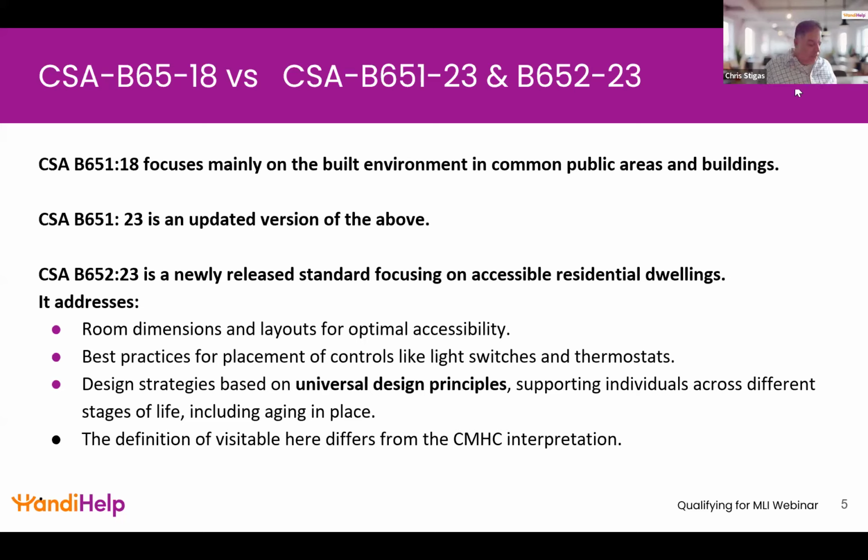And it gives you further detail on room dimensions, layouts, where light controls and switches should be placed. And also, the definition of visitable in the B652 standard is different from the CMHC interpretation. And we'll get into that in the next few slides. Next slide.